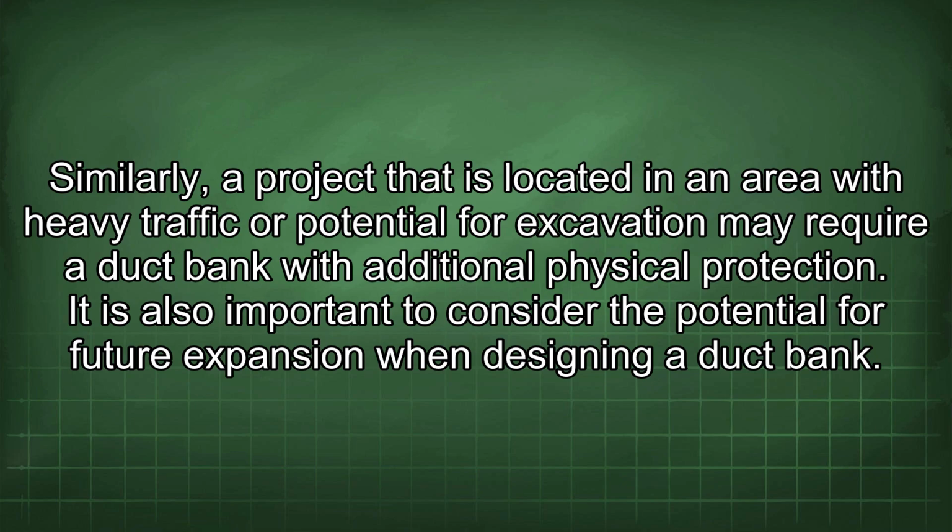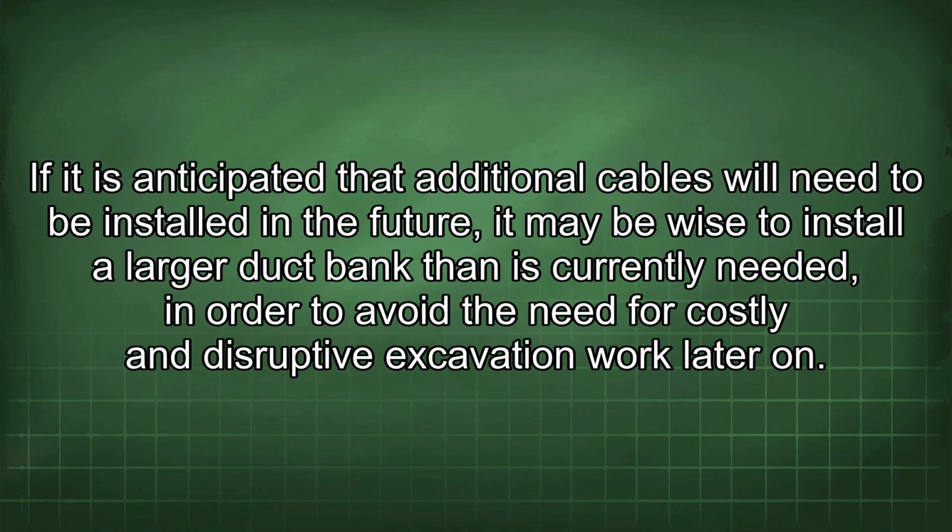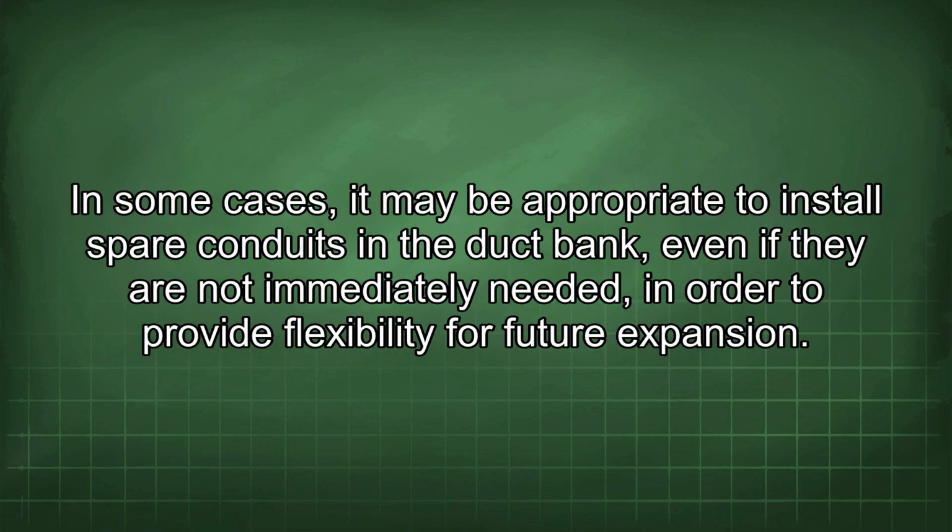It is also important to consider the potential for future expansion when designing a duct bank. If it is anticipated that additional cables will need to be installed in the future, it may be wise to install a larger duct bank than is currently needed in order to avoid the need for costly and disruptive excavation work later on. In some cases, it may be appropriate to install spare conduits in the duct bank, even if they are not immediately needed, in order to provide flexibility for future expansion.